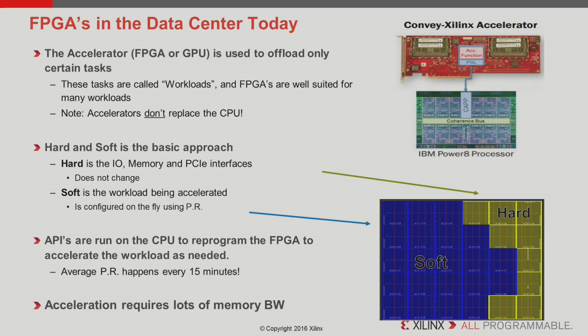So a single FPGA could handle all these different kinds of workloads because of the reprogrammability. The programming itself is done in what is called the soft logic. The hard shell is typically the peripheral interfaces, which are not programmed, like the DDR or PCIe, and the rest is programmed internally in the soft logic area.